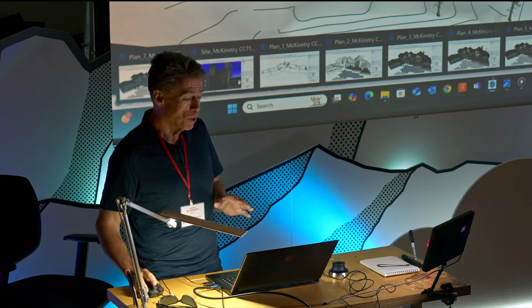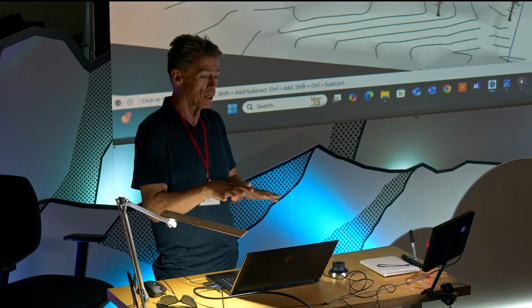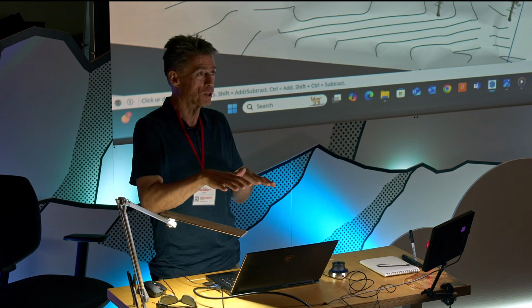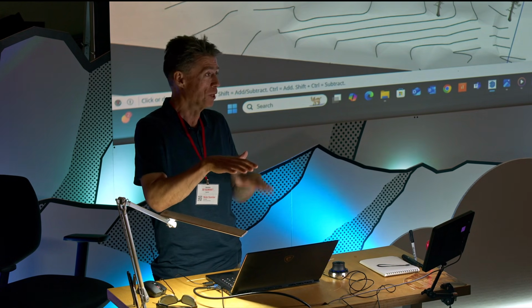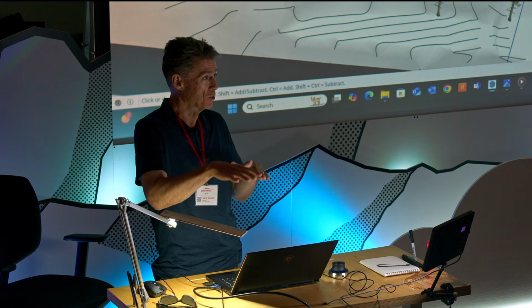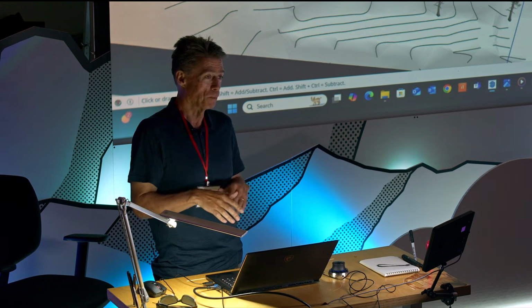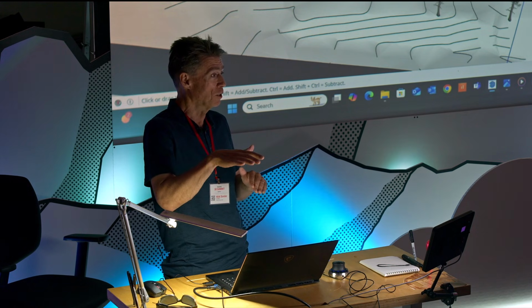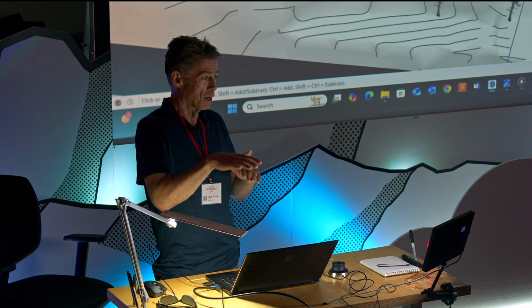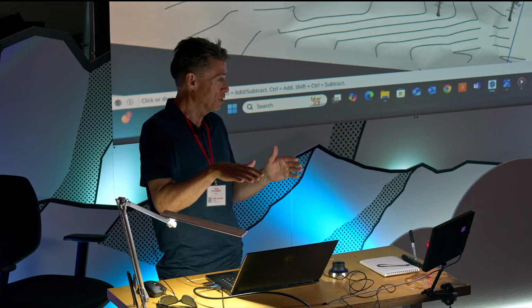From there, once I get a basic concept sitting on the site where I know, for instance, what my offset is between the garage and the living area, because that becomes a major aspect that you have to think about. Is a client anticipating they're going to have a 3-foot differential, or is there something where they can only tolerate the 6-inch differential?